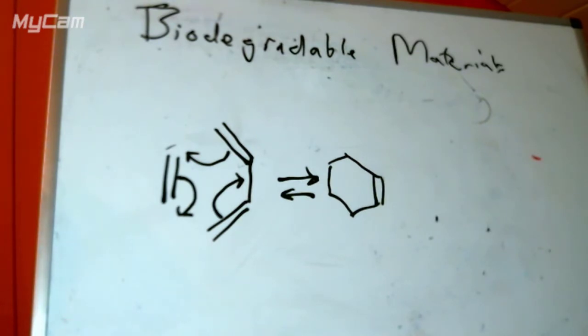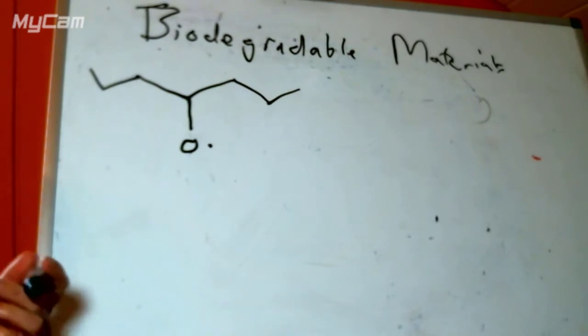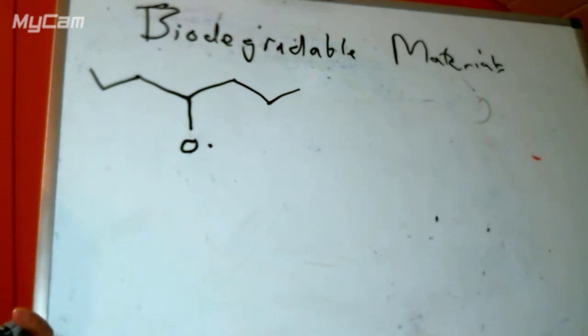If we're in a solid polymer, in the ground or on the top of the ground, then the probability that a radical inside the polymer finds a new piece of monomer is pretty much 0. The probability that it finds another polymer chain is way higher. So we've established that these radicals are very bad for polymers.